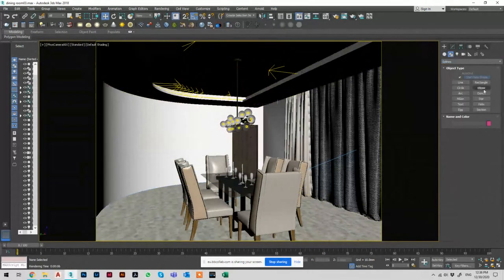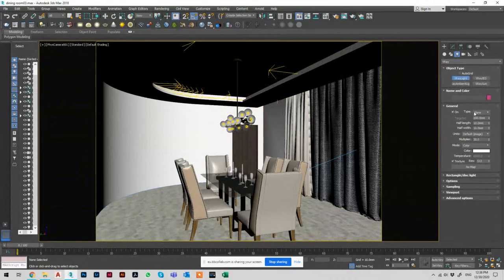One more type of lighting. Of course, this plain light, you can use it in multiple ways. So you have plane, you have dome, you have sphere, mesh, and disk. So disk is a circular vray light similar to the plane. Okay, a sphere is the sphere that we have inside here as well. So they're all the same. Mesh is when you create an object or a visible poly and you turn it into a light, which is something that is useful sometimes.